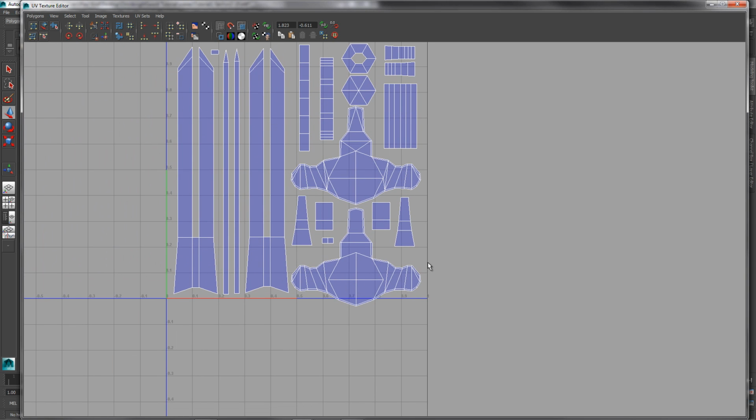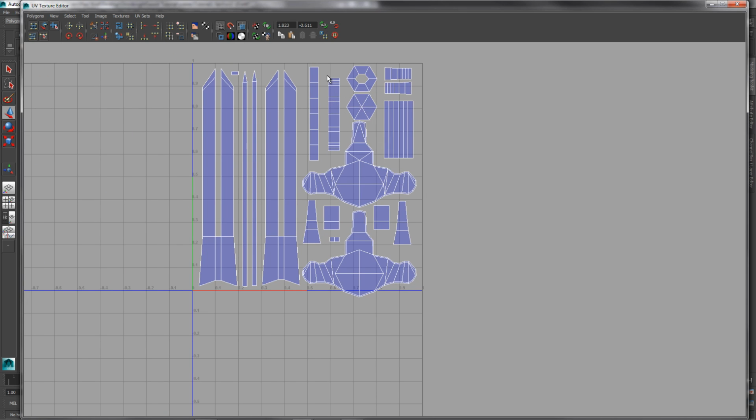Kind of bumping out off the bottom here. I wonder if I can get this a little bit better. I probably can. So I'm just going to move this guy. Once you have this done, it doesn't really matter because you're just going to rebake everything. So it doesn't matter if you move stuff around and adjust things, just so long as you don't expect to use the maps that you've already baked. Because if you are going to use the maps that you've already baked, then doing this is not going to be so good because you're going to be moving your textures around and it just won't line up anymore. So it's really important that once you get your bake, you don't move these anymore. But up until then, until you get your final bake, it doesn't really matter. You can kind of do what you want, just so long as you end up UVing and fixing and making things back the way they should.